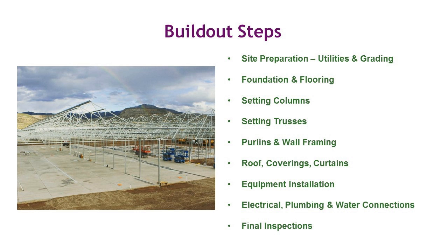Yeah, plan for expansion. And then also just to mention a little bit about the grading. That could be expensive too. When you're choosing a proper site, you want to choose one that doesn't have too many hills, because greenhouses like to be on a 1% slope, give or take. And to move all that dirt, especially in a very rocky environment, can be costly and could take a lot of time out of your project schedule. So site preparation and site selection go hand in hand.